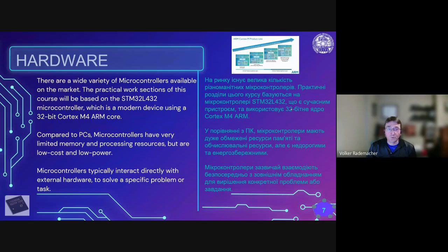If you're working in the field of embedded systems, you might very likely still encounter and need to program 8-bit microcontrollers. So the course will address some simple software techniques for very low memory and pin count microcontrollers and mention avoidable bugs or bug causes on 8-bit devices, which are usually related to interrupts and non-atomic instructions. If somebody doesn't know what non-atomic instructions are, it means non-divisible in this case. It has nothing to do with atomic power.